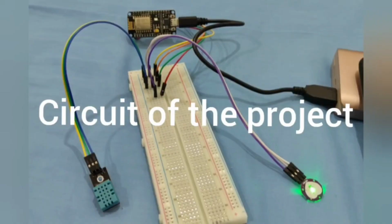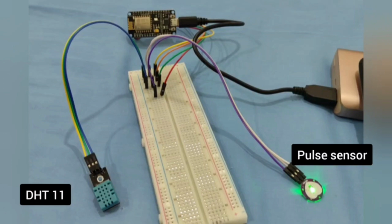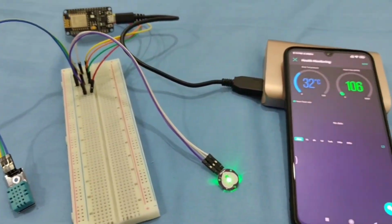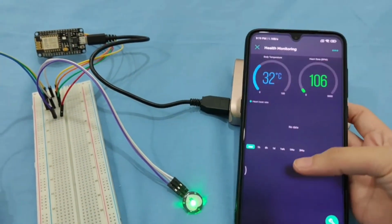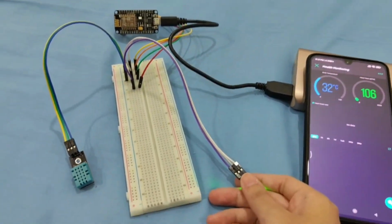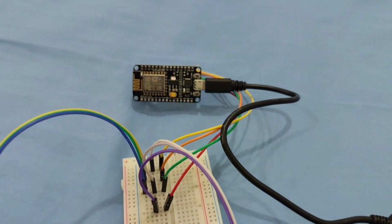Next will be the circuit of the project. As mentioned above, this project will consist of two sensors, which are the DHT11 and the pulse sensor. The DHT11 will be connected to pin D2, which is GPIO 4 of the NodeMCU board, and the pulse sensor will be connected to the analog pin of the NodeMCU board, which is A0. Once the circuit is applied, the reading will be displayed on the Blynk application as shown in the video. The blinking LED on the ESP board shows that a pulse is detected.